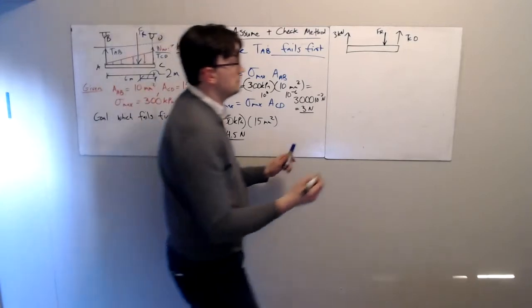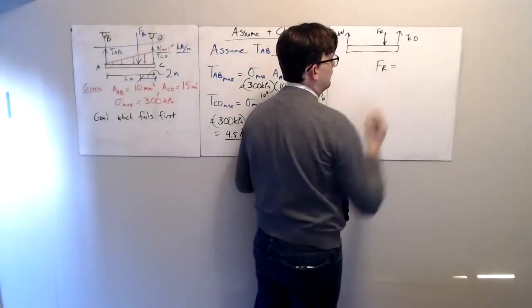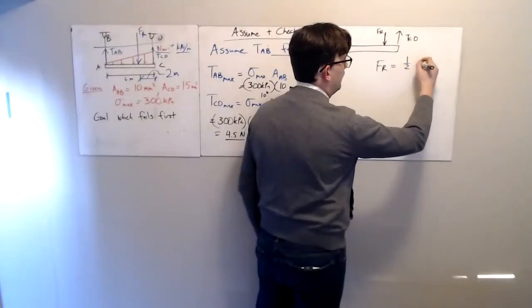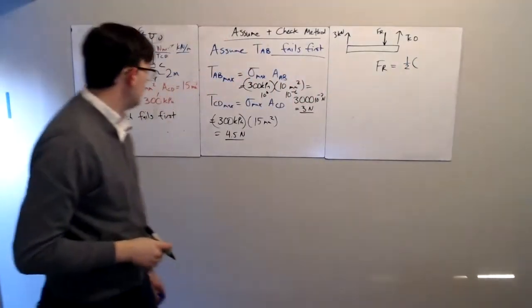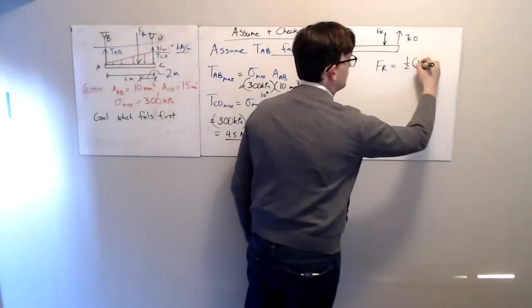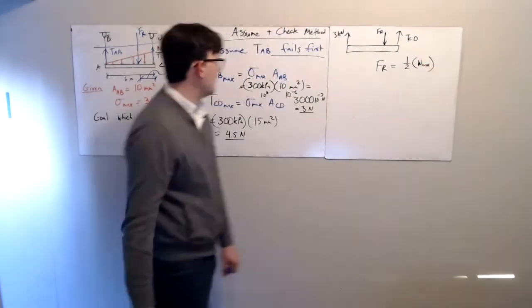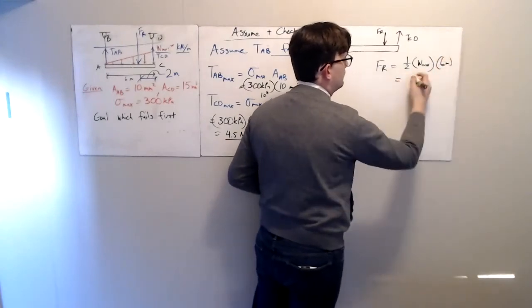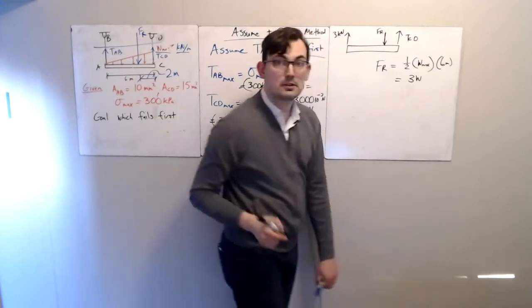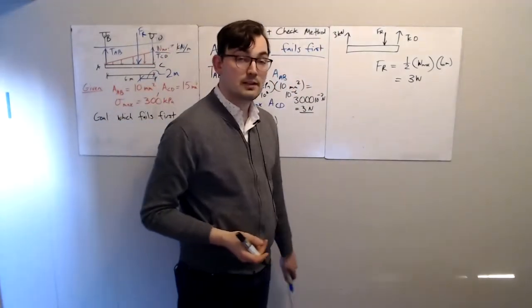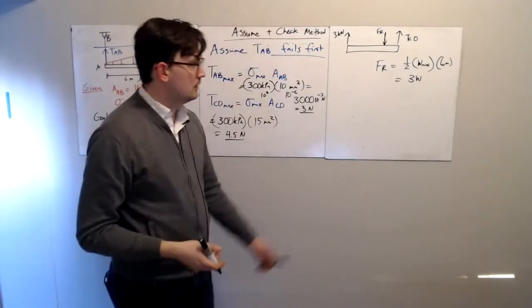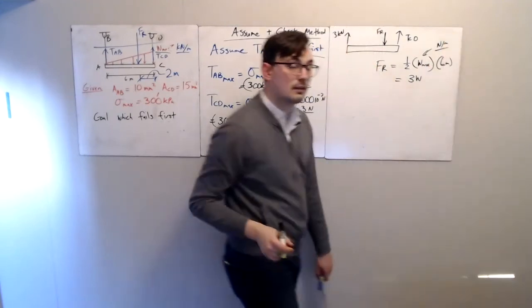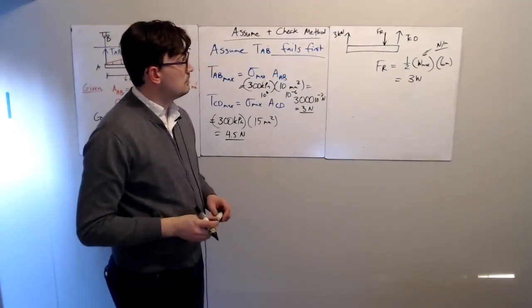Now, we already did our resultant force calculation. Our resultant force is going to be one half times our height times our length. In this particular case, we said our height is unknown. That's the W max times the length. Our length in this case is 6 meters. So this is going to be 3 times W. Remember, W doesn't have units. In the previous example, I guessed kilonewtons per meter. That was wrong. I would say it's probably going to be in newtons per meter based on the length here. But that's 3 times W.